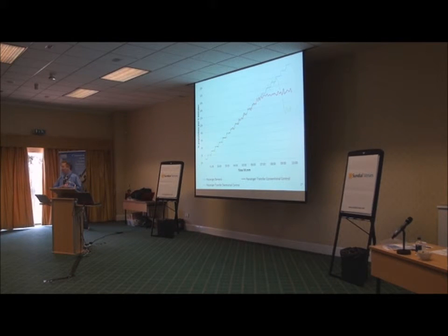Now the green line is even more interesting because that's destination control. And of course you'd expect because you get extra handling capacity, this is in pure up peak with destination control, you'd expect it to depart from the line later. So this one goes up, and although this one collapses, well, it doesn't. We start having queues with conventional control at 14%.